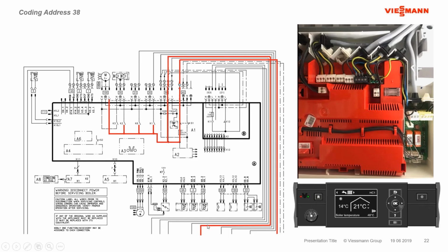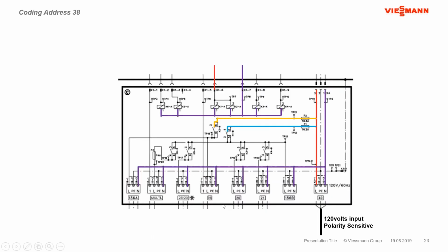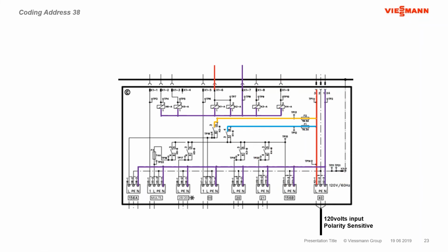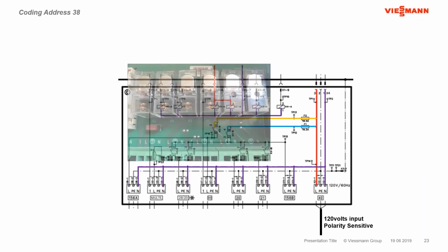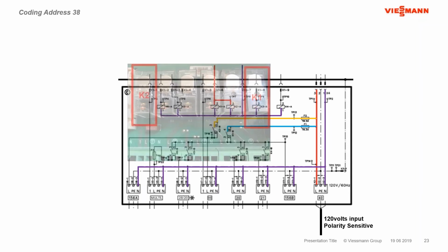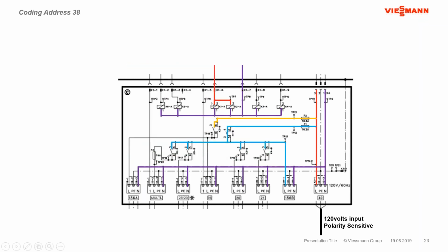But we'll sit down here back at the pump module, and when we power the boiler, basically press that power button, the power hits these two coils in the middle of our pump module. And those two relays will be K1 and K2. So we know that when these get energized, something down here is going to switch or close. So the first one we'll look at is K2. Oh, I'll back that up a bit. K2 here, or K1, sorry.